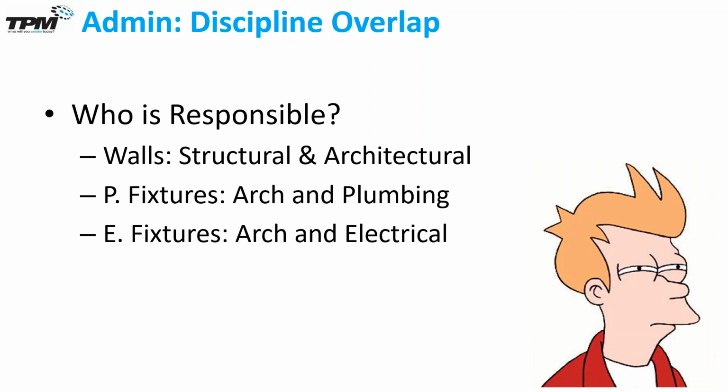Either that occurs because of the copy monitor command that's used by a structural engineer, or because they're using the architectural model and they're just taking those elements over and using them to flesh out the rest of the structural design. But the idea here is whoever's responsible ultimately for the placement of that item should be modeling that item.